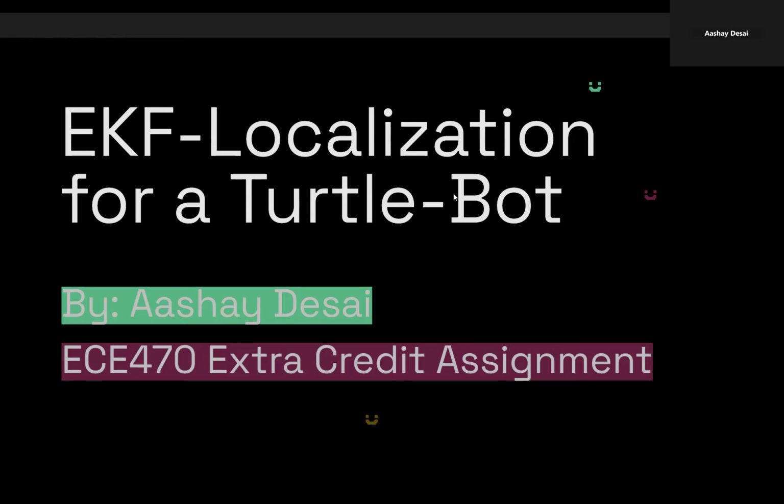Hi, my name is Akshay Desai, and welcome to EKF localization for a turtlebot. This is my ECE470 extra credit assignment, and in the next few minutes, I'll show how an extended Kalman filter, or EKF, fuses real encoder odometry and LiDAR measurements to keep a turtlebot localized with sub-decimeter accuracy.